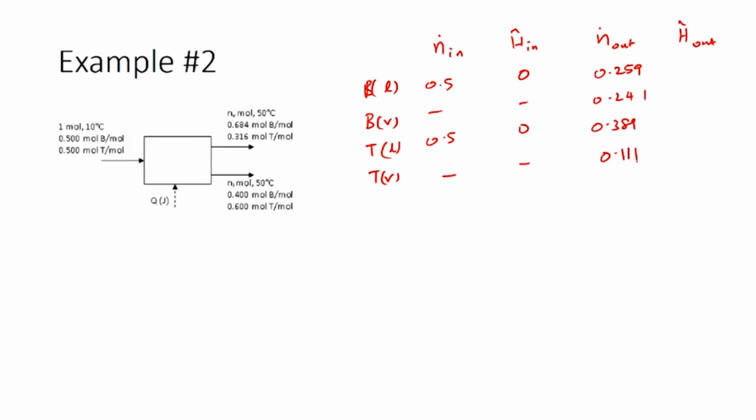The Ĥ1, Ĥ2, Ĥ3 and Ĥ4 that have been calculated would be: Ĥ1 is 5.332, all these are in kilojoules per mole and these other values are in moles, and we have toluene liquid, which is leaving, with a specific enthalpy of 6.340.